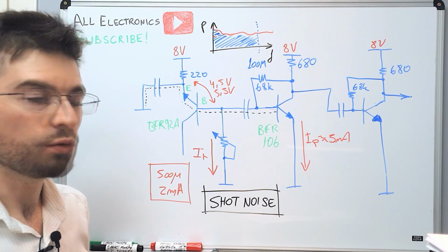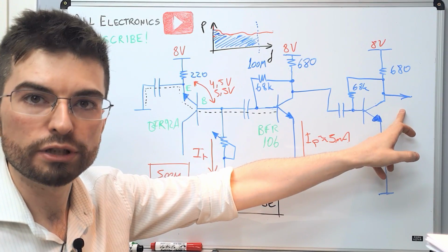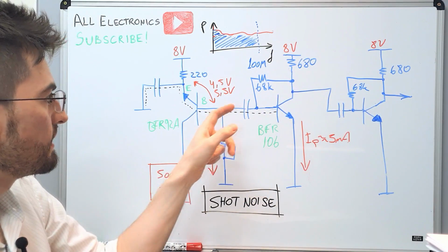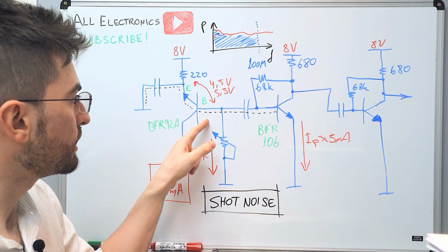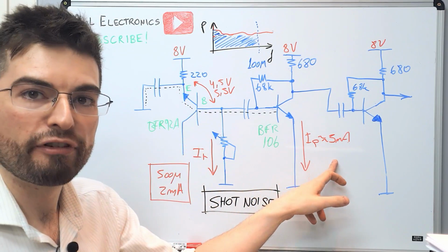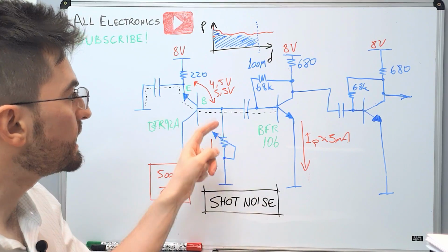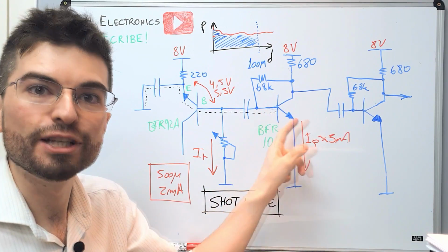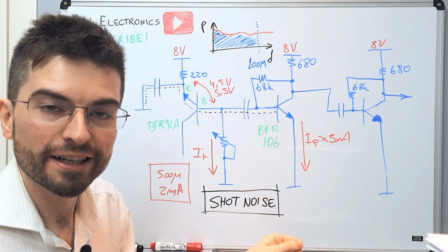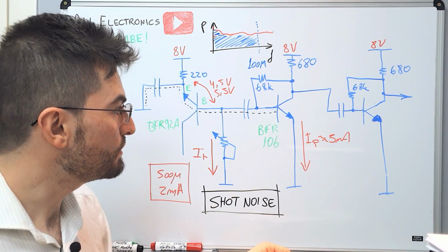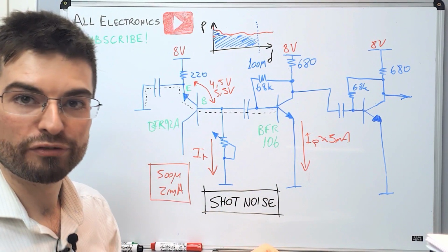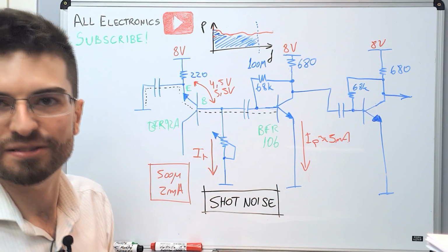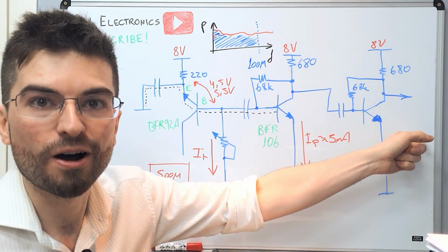That captured trace was the noise density here on the output. This noise density we are reading here is the noise density of the junction generator here, amplified by the amplifier chain, shaped by the gain profile of the amplifier chain. And of course, with the noise of the amplification steps, the noise figure, as I explained in the video I was talking about, with the added noise figure of the amplification stage. Here, for a noise generator, the noise figure of the amplifiers doesn't matter much because they are adding noise and we want noise in the output.